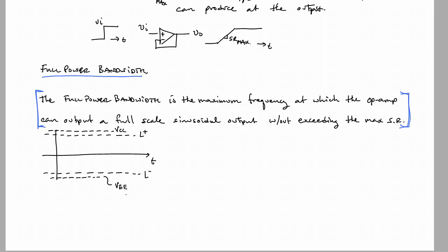Now there are some op-amps called rail-to-rail op-amps, meaning that the output can actually go all the way up to the power supply rails, but the ones that you'll be using in lab cannot attain that. So maybe you supply 10 volts for the power supply rails, but the op-amp may only be able to achieve 7.5 volts or 8 volts before it saturates and the signal gets clipped.